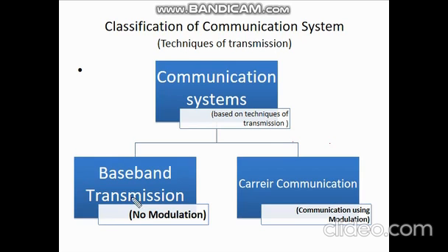The best example for a baseband transmission system is short haul PCM systems between two exchanges. Here in this case, you do not apply any carrier and there is no shift in the range of frequencies of the signal. These can also be applied over optical fiber communication, but this communication system is not advantageous over a radio link. Whereas for a long distance communication,